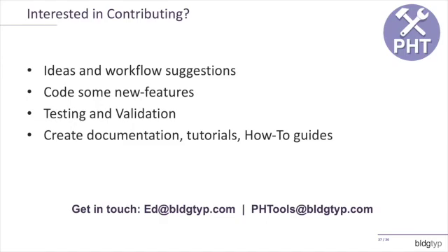So the Radiance solver that Ladybug is using, well, I shouldn't say it's always Radiance. There are a couple of different solvers that Ladybug allows us to hook into. We can use a couple of different versions of them, but we're talking about going from maybe 15 or 20 minutes for a really high fidelity solution down to maybe a minute or two for a really, really complex scene with millions of polygons. You can do that type of assessment really quickly on the Rhino side in a way that would take literally double digits of minutes to do on the Design PH side.